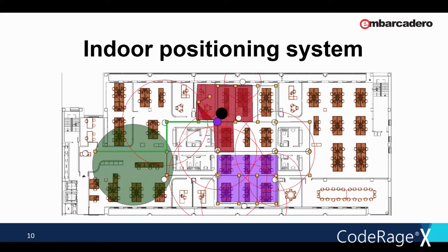An indoor positioning system is a solution to locate objects or people inside a building using radio waves, magnetic fields, acoustic signals, or other sensor information collected by a mobile device, in our case Bluetooth Low Energy. As the main tool to solve this problem in our component, we have made use of a special probabilistic filter called particle filter localization, also known as Monte Carlo localization, MCL.